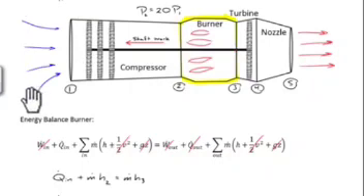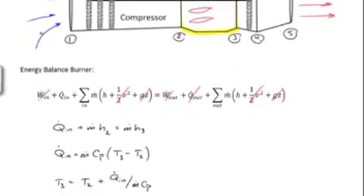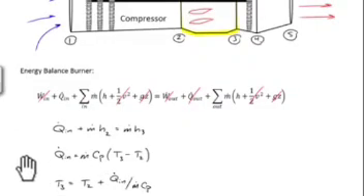So again, for an ideal gas, we'd expect Qin is equal to m Cp times the increase in temperature as the air exits the burner itself. In that case, if we know Qin, we can calculate T3, the temperature at the exit of the burner, just by rearranging this algebraically. We know everything. If we know Qin, we can find it.